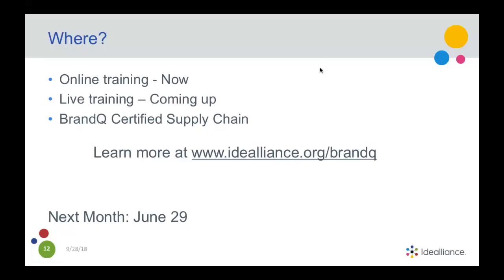So I think you want me to talk about the fact that if you've got your device certified and then you test that instrument and assess it, let's say once a month over the course of a series of months, and you can prove that that instrument is not varying outside of your expectation or level of delta E tolerance, then there's no reason that you need to get that instrument sent back to the factory to be recertified.